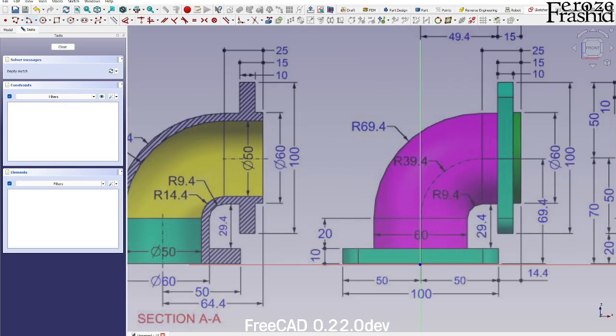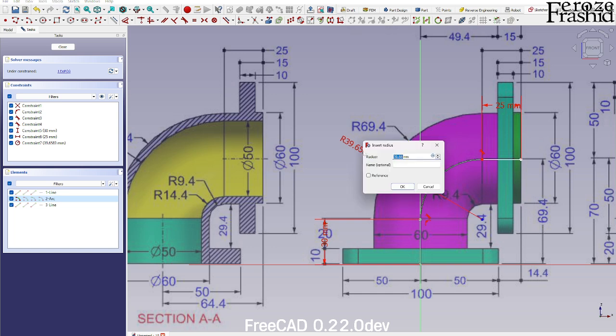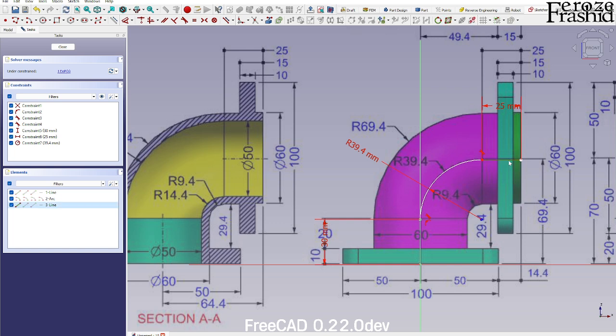so this curve, I'll start with a polyline. Now come up here, so that's like there, and then we'll go there and hit M, M, and M. That's our curve, and we'll come up to here. Okay, so this, I want to apply some dimensions. This is going to be 30, and this is going to be 25, and this is radius 39.4. 39. Okay, we have one more degree of freedom, which is this. It will be horizontal, and that's keyboard shortcut H.